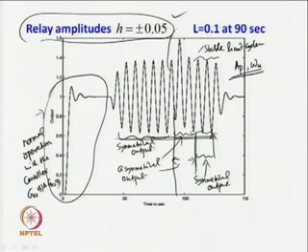If you make measurements from this, then you will not only get incorrect peak amplitude, but also you may get incorrect critical frequency or ultimate frequency from the limit cycle output. So, this is very important for us.